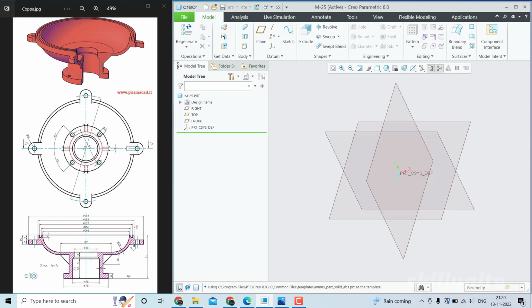We are going to do this sketch in this triangle portion, and this portion what you are having here is going to come only on these two sides. This triangle, like a stiffener or support kind of thing, is taking place at 4 places. So we have to do it later. So what we are going to do is just create this shape, and then with respect to the center axis, we are going to make a revolve.